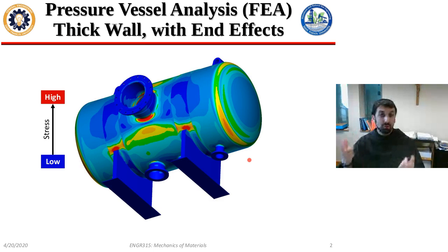And as a result, it doesn't just apply to things like this port here or other interruptions in the length of the vessel. It also applies to things like this, which you might think of as an effect of a sudden change in curvature, like there's a fillet here, a stress concentration. We're ignoring that. So we're assuming some uniformity and symmetry in our stress distributions.